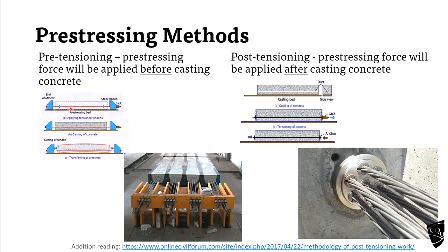Now you put the concrete over there. Remember, the steel is under tension, but it is fixed at both ends. So you pull the steel, fix it at both ends and put the concrete. Then after 6 or 7 days, not 28 days, we don't wait, after 7 days we cut the wires.